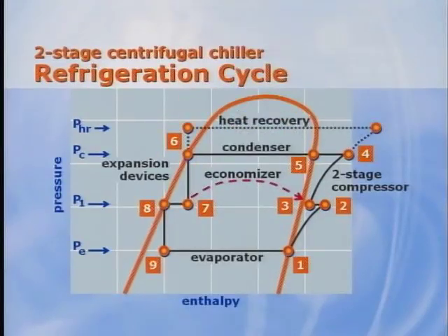Just like positive displacement compressors, power consumption is increased due to the higher pressures associated with heat recovery. However, the differences in the pressure enthalpy chart between a positive displacement compressor and a centrifugal compressor are not important when heat recovery is concerned, but the physical differences in the compressors themselves are.